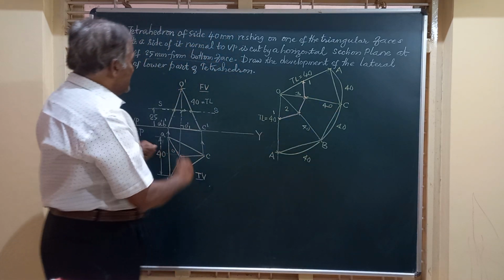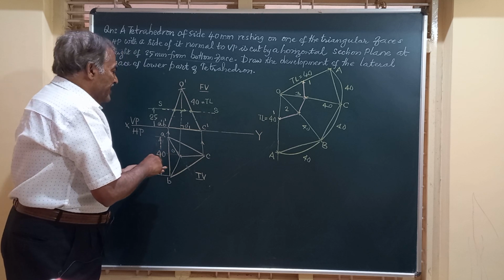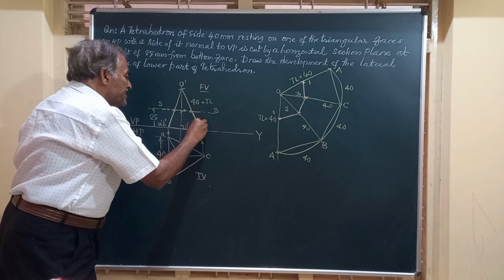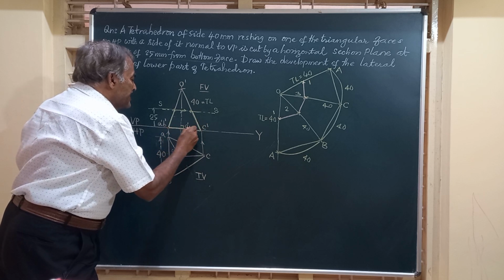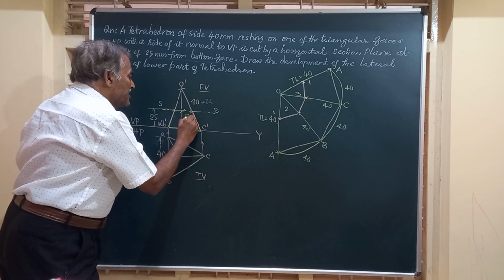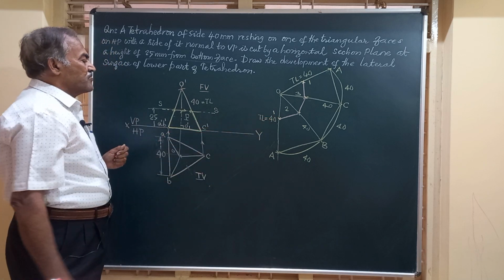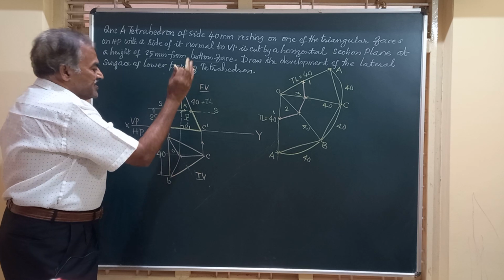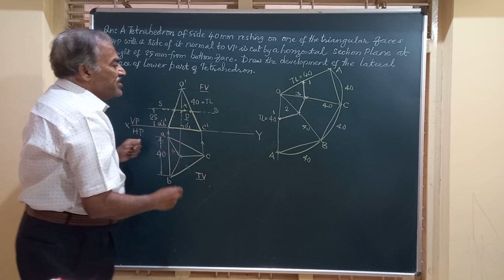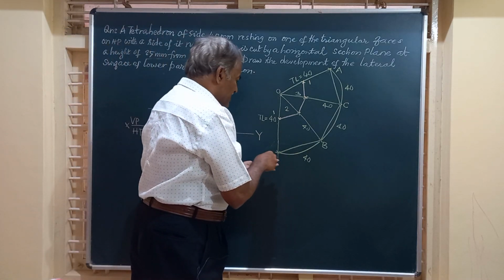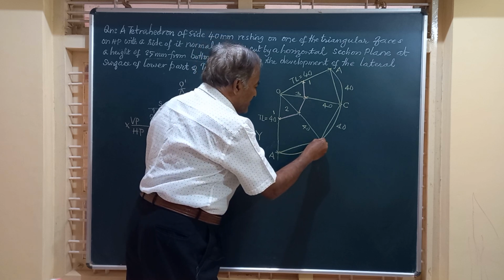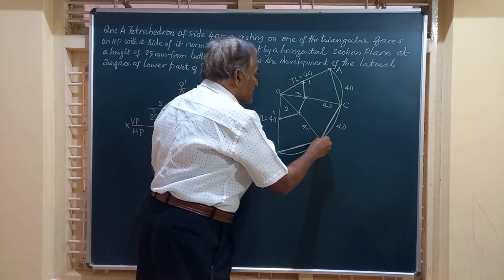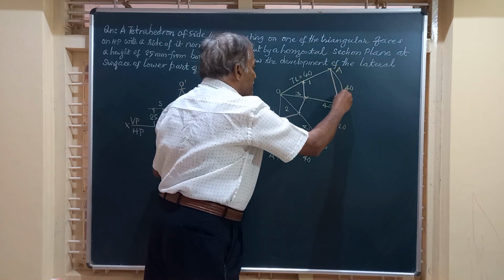And friends, the portion below the section plane, that is this part of the tetrahedron, is retained. We will call this part P, and the development we are trying for is part P. So the portion above that is thrown out, assume it is not there. So the complete base should be there. Complete base means you will have the edges AB, BC, CA.